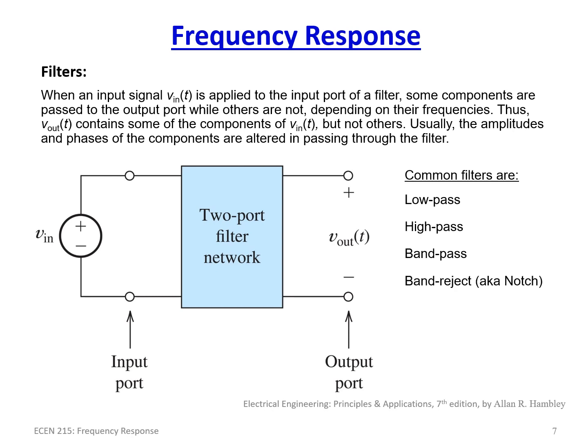And then the inverse of that would be the notch filter, also known as the band reject filter, where all frequencies up to the lower cutoff point are passed through. Then you do not pass the range of frequencies you've specified, and anything above the high cutoff point you then pass through to infinity. So it is known as a band reject filter, and we'll go over each one of those in just a moment.